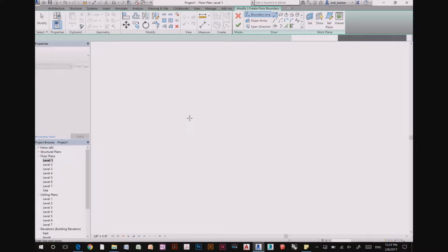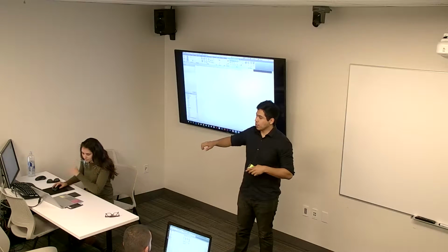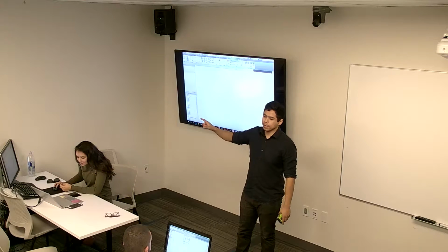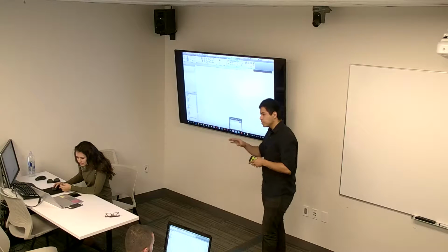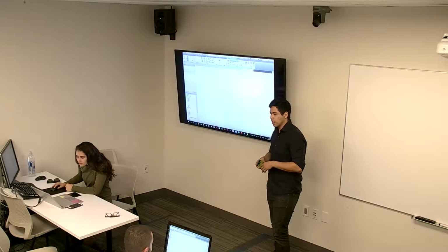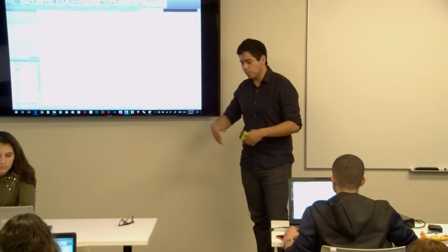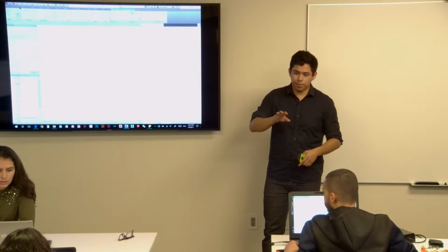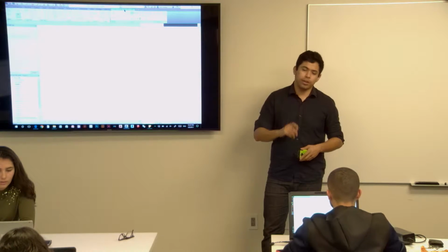If you hit the line tool and you hit the white space and just hold it and drag it across, you should see a line be created. Usually it'll come up with numbers on top. You could just type in a certain distance, usually like 15 feet or 10 feet. Or if you want to start building a house, you have a floor plate that's 40 feet. So if everybody can type in 40 feet, just with your keys, type in 40 and enter.